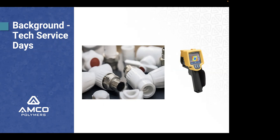So I started doing it, and I noticed right around 200, 210 degrees, my parts are coming out and they're just kind of distorting by the weight, or you can push on them and they become oval very, very quickly. So anything under about 200 degrees, they're pretty much set up and pretty rigid and they hold their shape. So I said, okay, I'm going to keep decreasing my cooling time until my hottest part comes out about 200 degrees, knowing and understanding that my mold's going to heat up and over time things are going to change a little bit, but I want to be around that 200, 210 degrees.